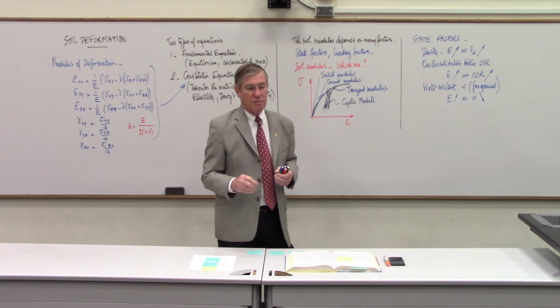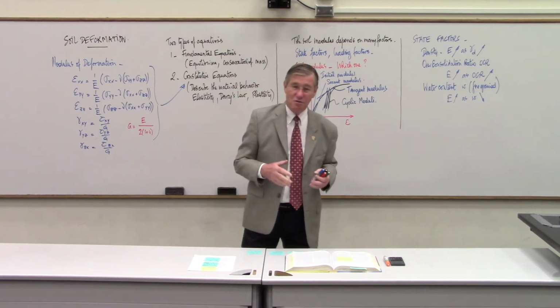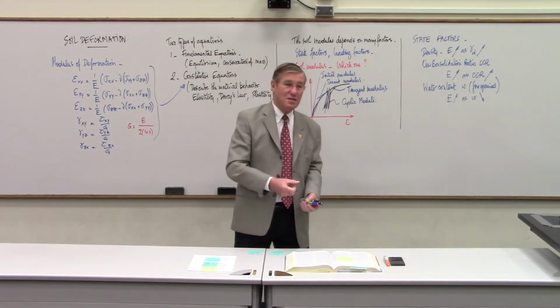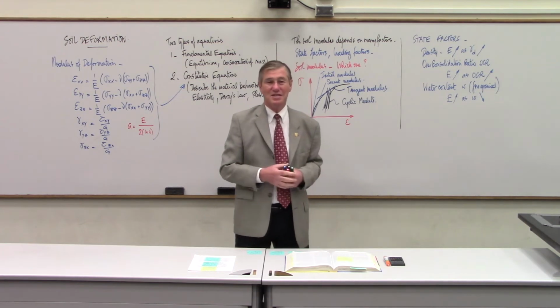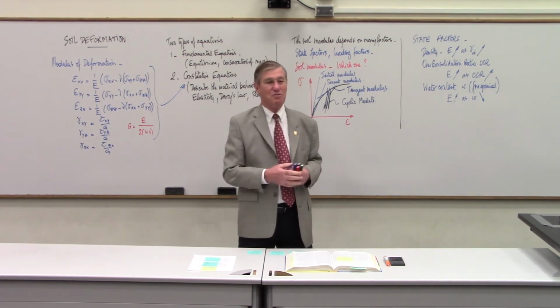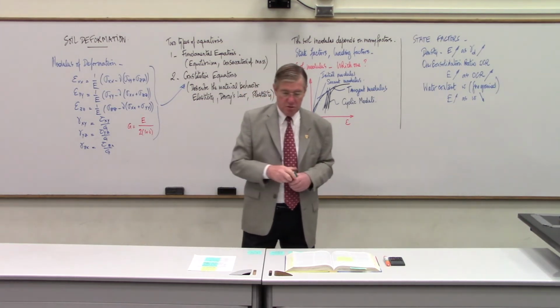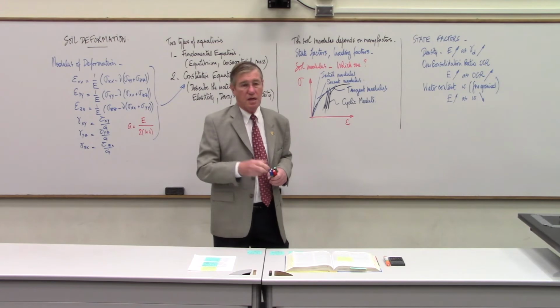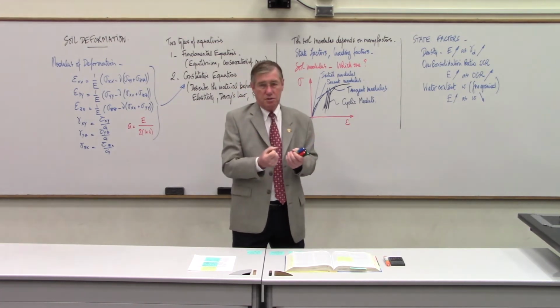At the same time, the silica in the soil or other minerals is attracting the water. And so the water is sitting there, and the relative humidity in the air in the room says, come over. And then the silica particles and the minerals say, no, no, you're not going anywhere, I want you to stay here. So the water is pulled in tension between these two mechanisms, and that tension is actually drawing the particles together. And that tension can be extremely high.